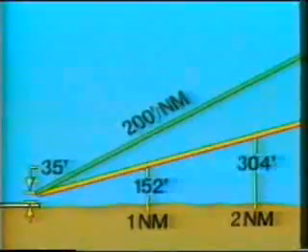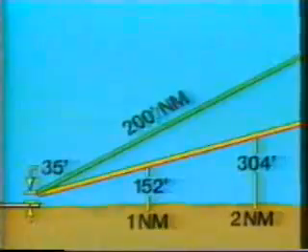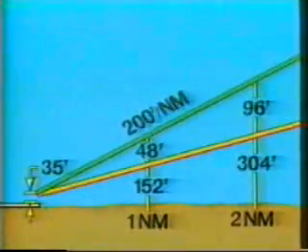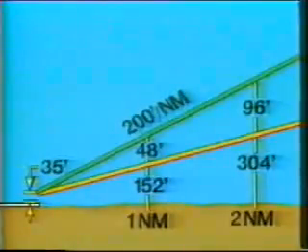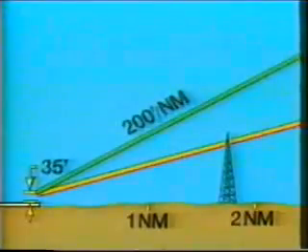A slope of 152 feet per nautical mile is assessed for obstacles. If none penetrate this slope, the 200 foot per mile gradient provides you with a minimum of 48 feet of obstacle clearance for each mile of flight. If obstacles do penetrate this slope, special avoidance procedures are specified.